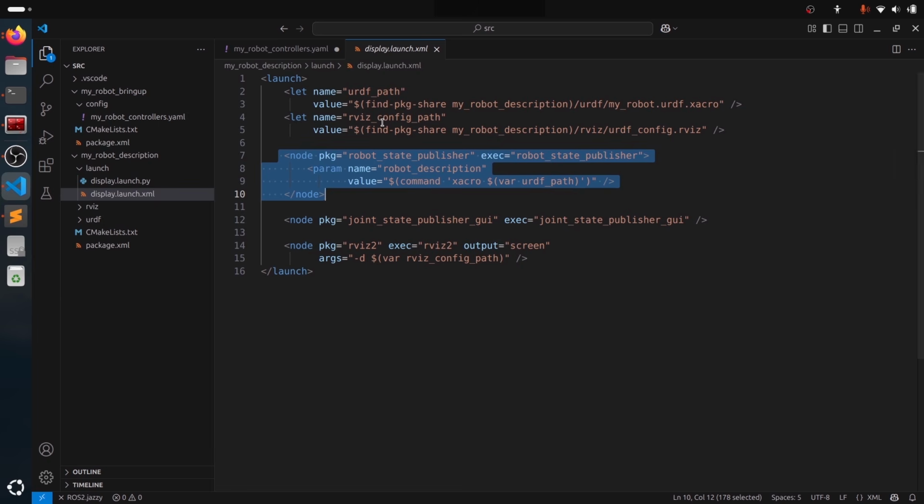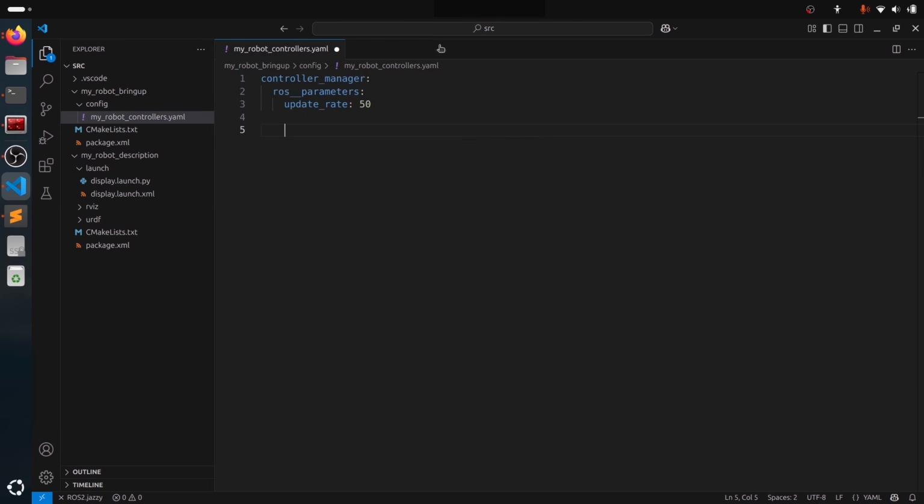What we have done here in this example is just to use a fake joint state publisher with a graphical interface, so we can, well, fake the joint states. But we don't want to fake the joint state for a real robot or real project with ROS2 control. So we need something that's gonna get the data from the hardware and publish it on the joint state topic.